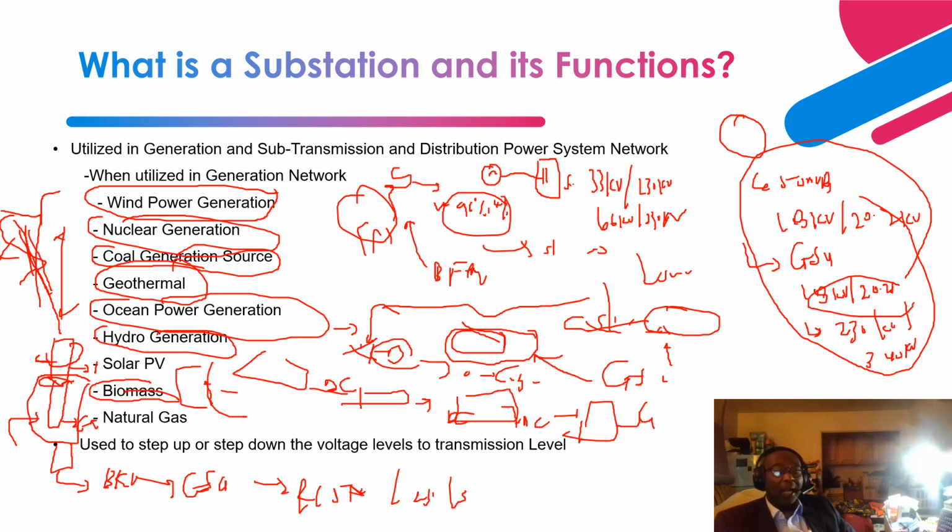As the steam rises to the higher section of the boiler, it gets reheated, because the goal is to get the steam as dry as possible before it is fed into a steam turbine generator. The steam from the boiler is quite close to 100% dry, let's say about 96%, with about 4% moisture in it.